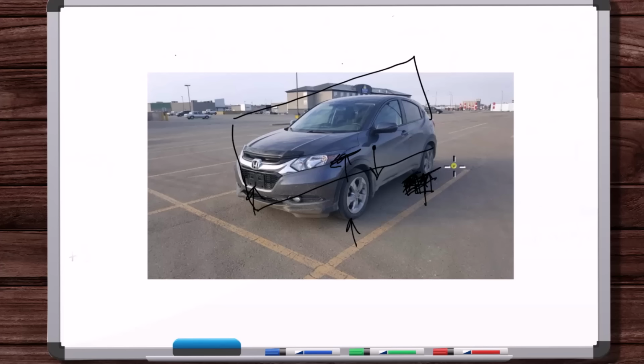Well, if you have a case where you can do a planar free body diagram, the idea is, if we took these back two tires and we reduced down these distributed loads and then combined the distributed loads on this tire and this tire, we combined them all together and then found a resultant force and the location of that resultant force. The resultant force is going to be in the plane of symmetry. It's not going to have any component coming out of the plane of symmetry. It's going to be located at the center between the two tires.